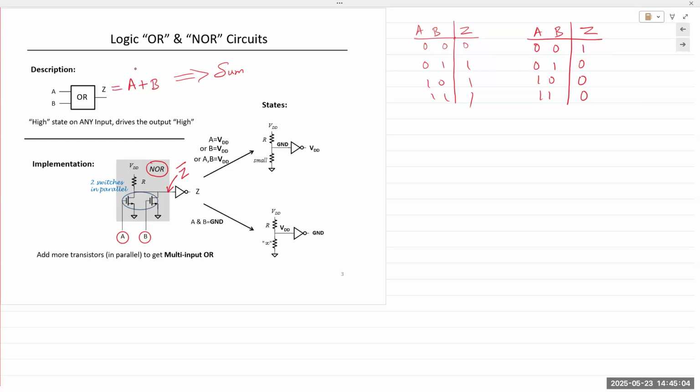If we are talking about an OR gate, we obtain Z bar. So if we wish to have an OR gate, we connect a separate inverter at the output of those two transistors. So we need at least 3 transistors to have an OR gate. Okay, so by default, we obtain a NOR. And on the next page, we'll see by default, we can obtain a NAND gate. So again, these are some straightforward switches. Either one of them is on, the output will connect to ground. Okay, so we get a NOR gate.